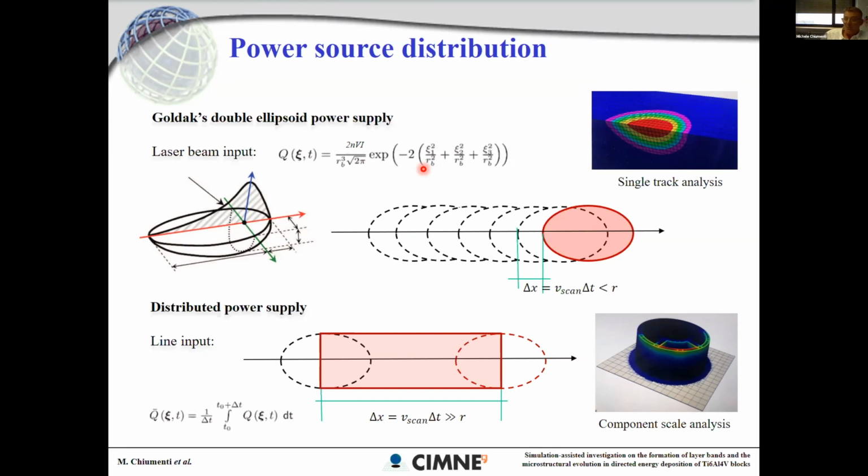This is part of the, let's say, mechanical modeling. The answer is that we have two different constitutive models, one for the solid phase and one for the fluid-like phase. In both cases, we are using a mixed formulation. In the solid phase, we are using a UP formulation, a mixed displacement-pressure formulation, which includes the stabilization for this kind of problem.